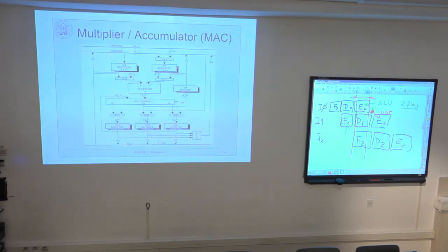We have shown this. So going further with this multiplier unit, more or less it has the same conceptual architecture. Again, it is like a binary operation. You have X branch, Y branch. Again, you have two registers, MX0, MX1, MY0, MY1, which can be selected as input arguments for multiplication.